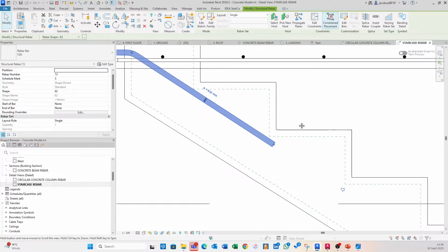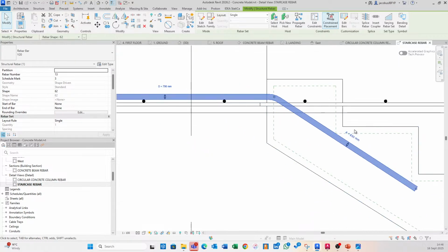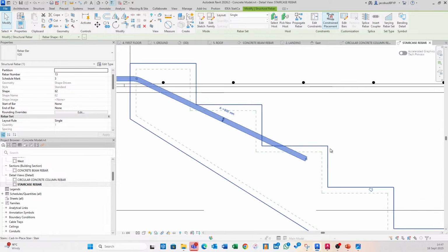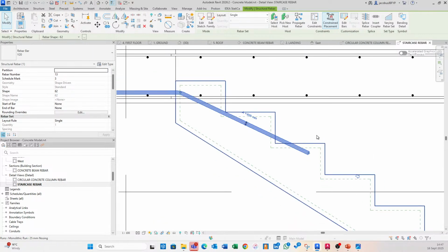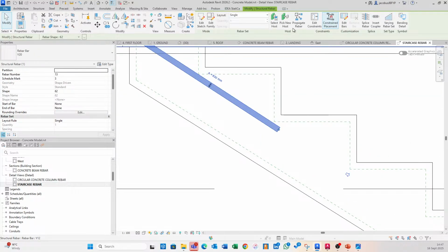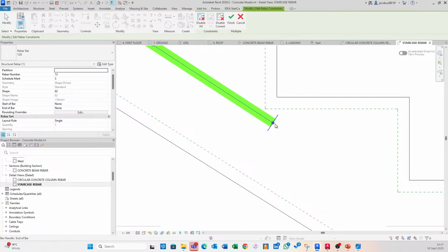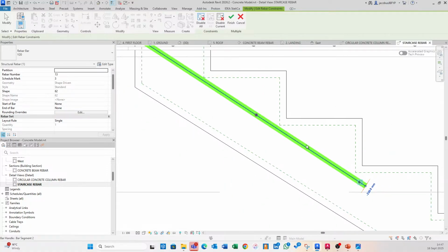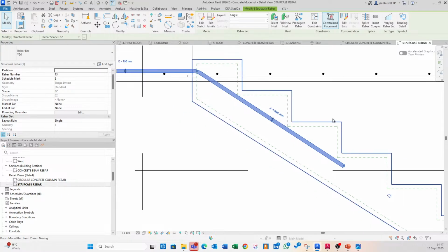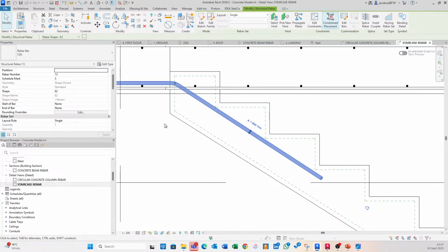Now this becomes frustrating. So you'll see if I click here and I make that 800, you'll see what happens. Now, for the life of me, I cannot tell you why that happens the way it does. It's very frustrating, but there is a different way to work around that. It's to click on Edit Constraints, to click on that guy, and then to modify that value and to see how that affects that A length. All right, that is now the host.